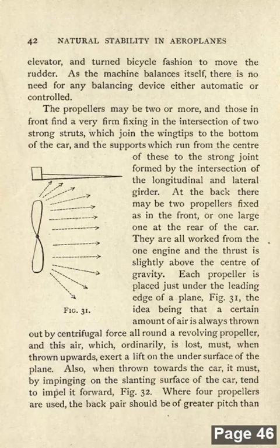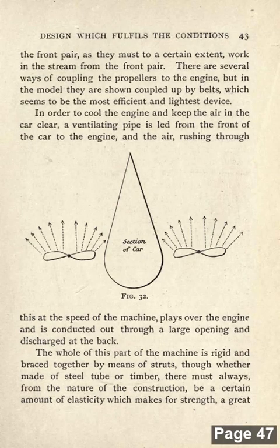Fig. 32. Where four propellers are used, the back pair should be of greater pitch than the front pair, as they must to a certain extent work in the stream from the front pair. There are several ways of coupling the propellers to the engine. But in the model they are shown coupled up by bolts, which seems to be the most efficient and lightest device.